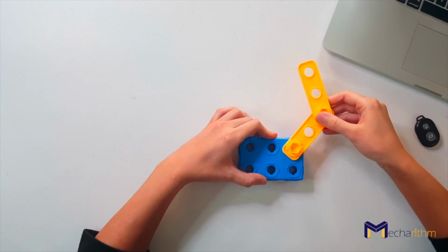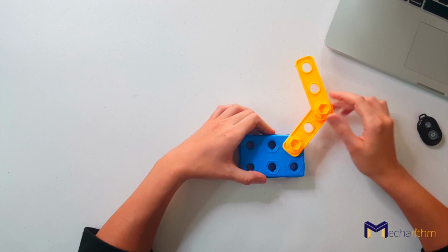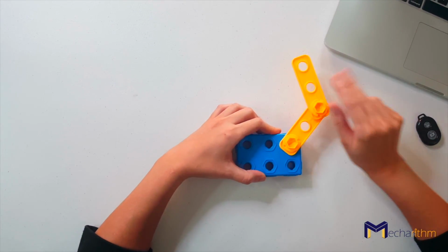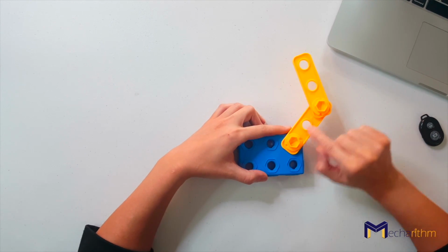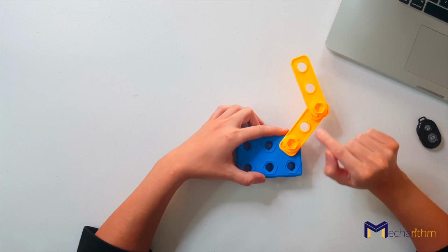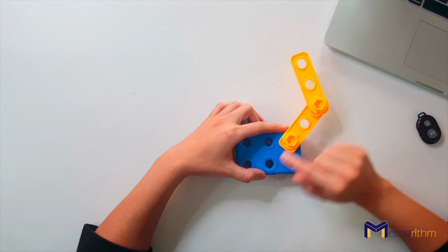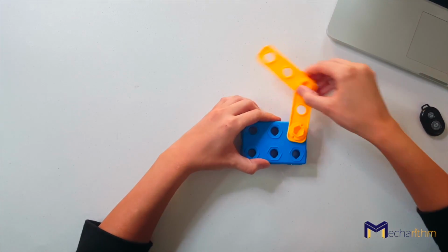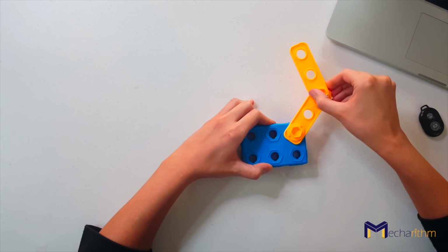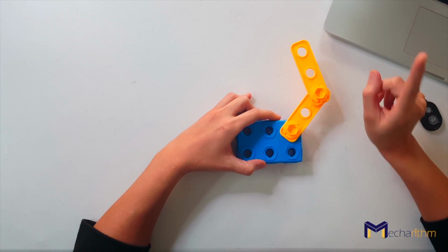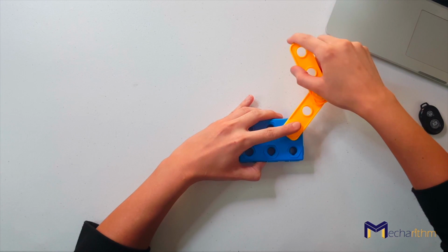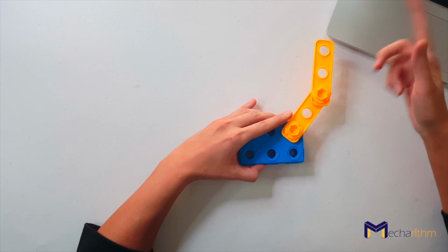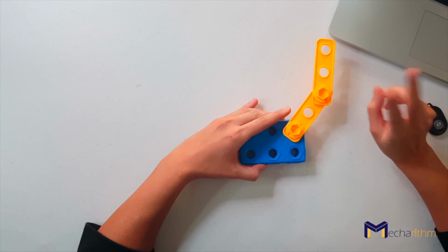So for instance, in this 2-dimensional planar robot, each rotational joint puts 2 constraints on the motion of the link. So the link cannot move in the X or Y direction. It only can rotate around the Z axis. So it only has 1 degree of freedom. So each joint provides 1 degree of freedom. So the overall has 2 degrees of freedom.